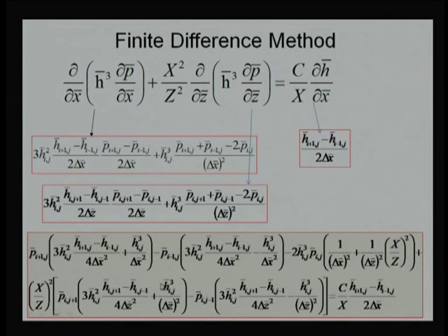An interesting thing is that after rearranging, we are getting a much lesser number of cubic terms. A cubic term is coming only in h I j, we do not have any other cubic term. So, the number of calculations will be reduced with this kind of formulation. The only problem is that it involves more terms compared to the terms we saw when using the finite difference method in hydrodynamic lubrication.